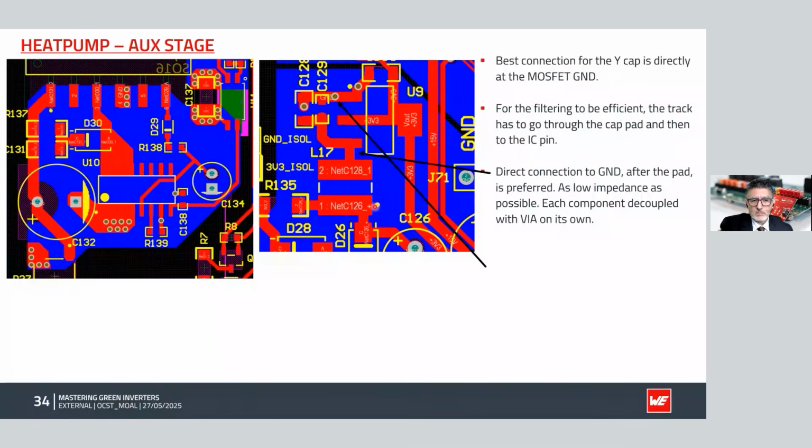Some of the various layout and tracking considerations as well with that LC filter I've just mentioned earlier. That's the L. These are the two capacitors. So you directly track between the L and the two Cs before you go across into the next IC, which was that voltage regulator LDO.